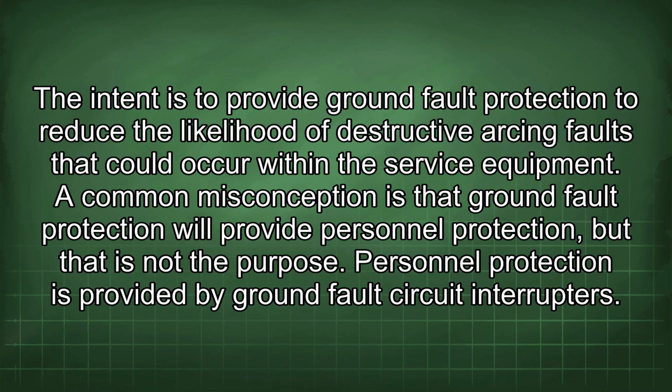The intent is to provide ground fault protection to reduce the likelihood of destructive arcing faults that could occur within the service equipment. A common misconception is that ground fault protection will provide personnel protection, but that is not the purpose. Personnel protection is provided by ground fault circuit interrupters.